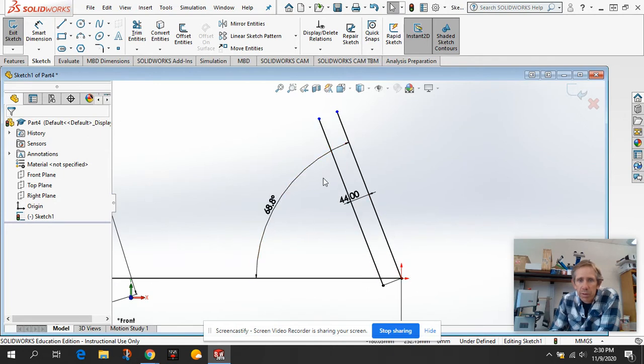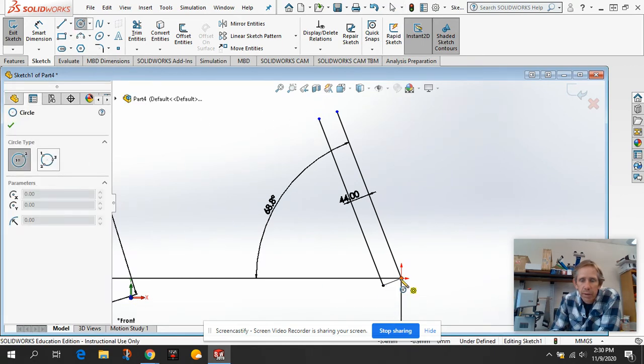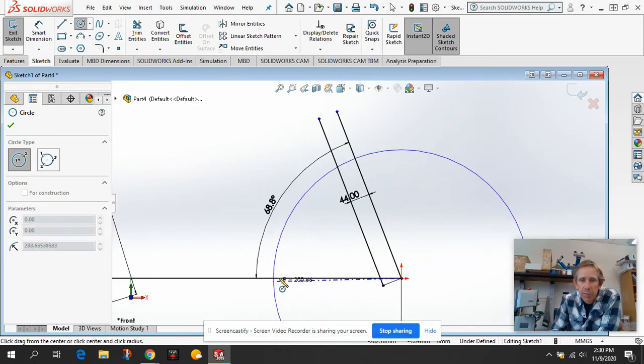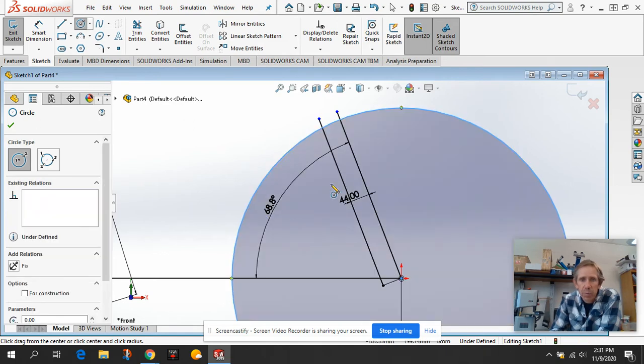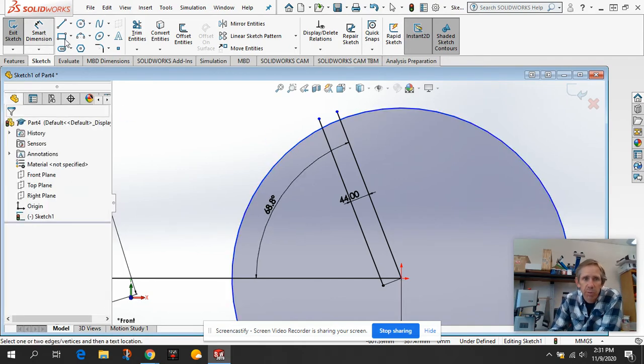Now, using all of that information, we're going to put in our axle to crown length and determine where our head tube needs to go. I'm going to draw a circle here at our front axle, pull out a certain distance kind of randomly, and then we need to dimension this. Again, it's drawing a full circle, but we only needed the radius, so I have to do a little bit of math when I dimension it.